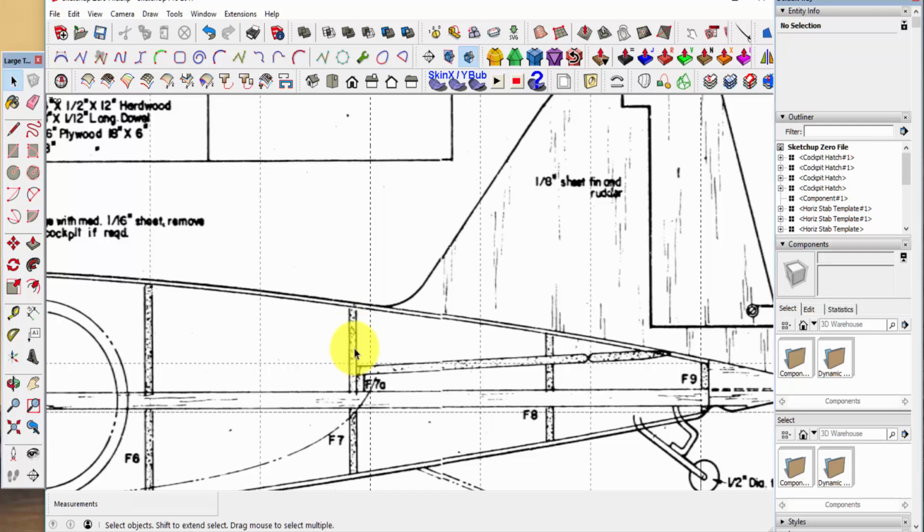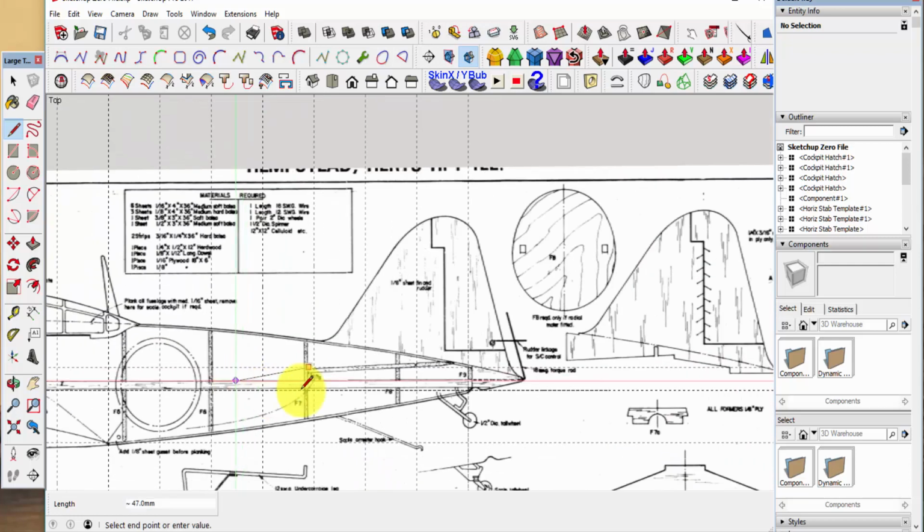So to do that, we'll start there, and we will come in on the line that we decided we were going to put it on, and we're going to move aft just off of the model entirely. We'll come down again. It's an arbitrary amount, but enough to make the poster board stiff enough to handle. Then we'll come down to here. We'll move then over to a known former. We need a known former to align it to.